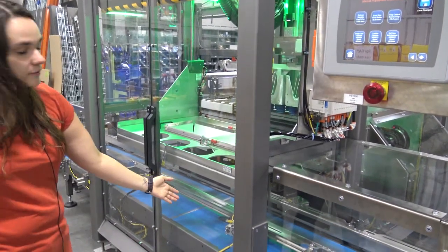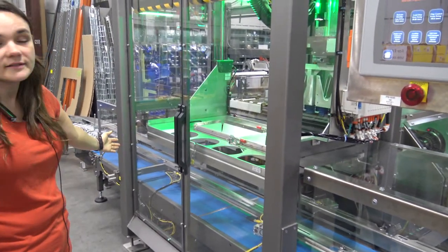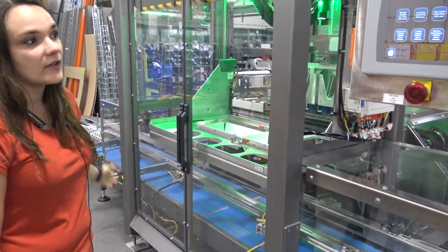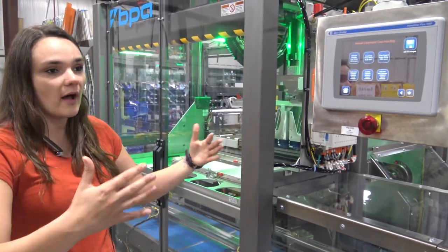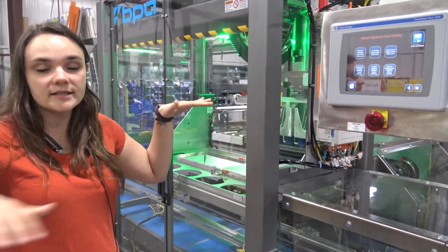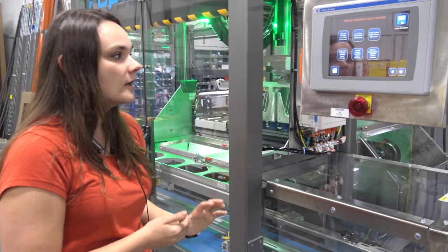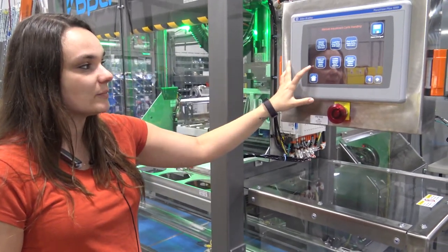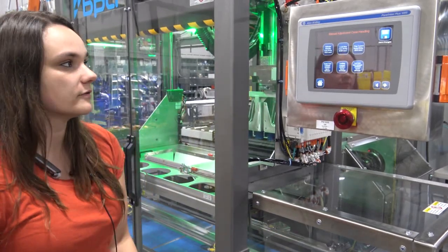So you have your load stop, which is your first delay. Your second delay is going to be your case at standby delay. And then we have our flap control down delay, which is when a case exchange happens, you will have the flap control come up to release cases. Once cases are settled in place, it'll come back down after 150 milliseconds currently. This is where we can adjust the speeds for our empty case, our loading conveyor, and our full case conveyors.